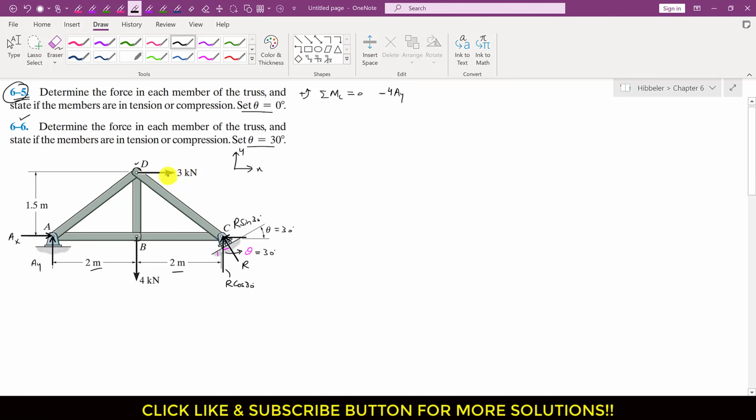Similarly, this 3 kilonewton force is also producing the clockwise moment about that point C. So I will write minus 3, and the perpendicular distance of this 3 kilonewton force from that point C is 1.5 meters. So I will multiply this with 1.5, right? Similarly, this 4 kilonewton force is producing the counterclockwise moment about this point C. So I will write plus 4, and the perpendicular distance of this 4 kilonewton force from that point C is 2 meters. So I will multiply this with 2, and this is equal to 0.